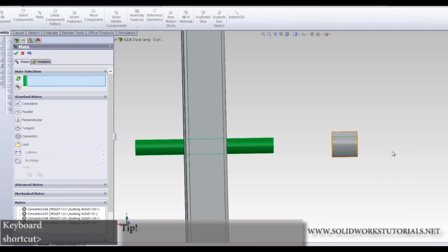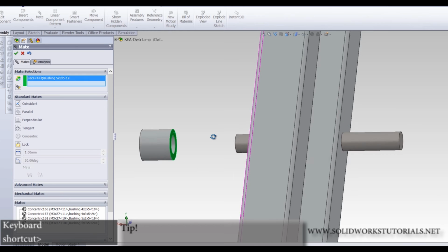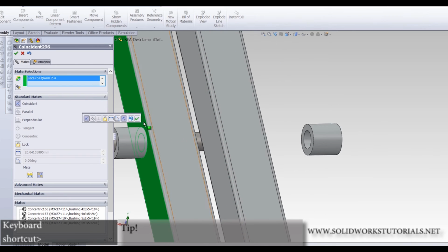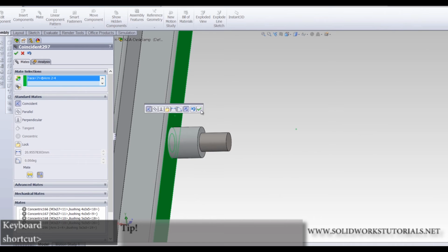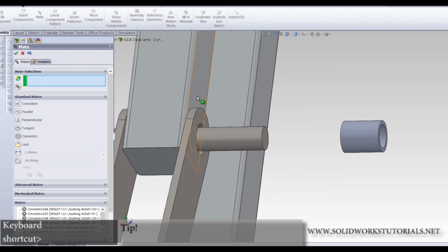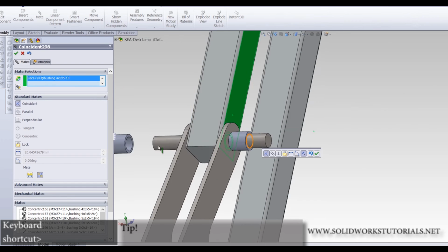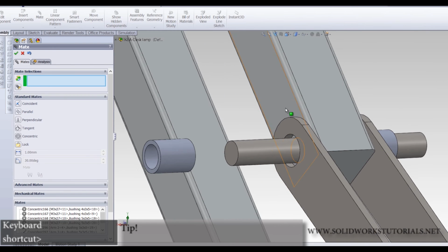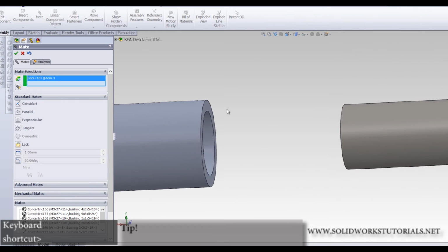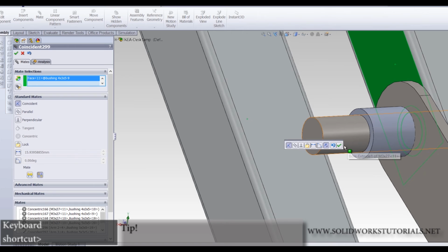Now all 4 bushings here should be connected directly to the outer surface of the arm. By that I mean for the upper ones it is obvious, but for the lower one, make sure not to choose the outer surface of the A-joint, but the arm. So the bushing would go through the hole on the A-joint. Very good.